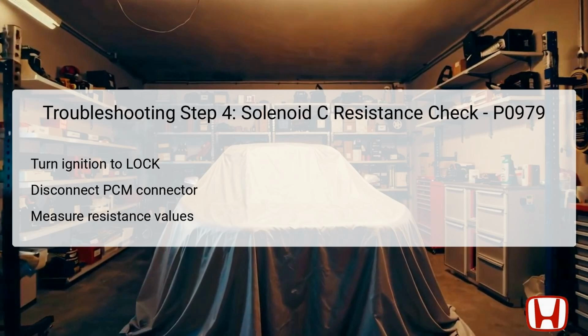Proceed to disconnect the PCM connector C, which typically houses 49 pins, 49P. With the PCM connector now disconnected, it's essential to measure the resistance between designated test points, specifically PCM connector C pin 21, which is green, GRN, and a ground point on the vehicle's body. The goal is to determine if the resistance falls below 13.8 ohms. If the measured resistance passes this criteria, you should proceed to step 5.